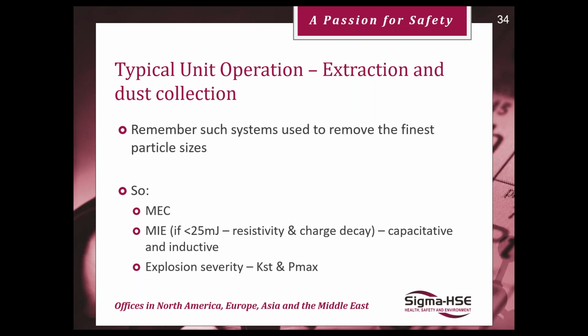So it's the most combustible material. The concentration in your ductwork between your process and your dust collector needs to be below the minimum explosible concentration, which is easy to achieve. You just need to know how much dust you're going to produce against the airflow provided by your ventilation.